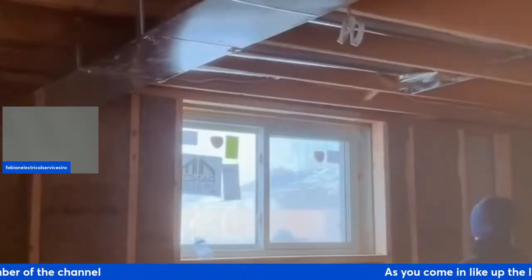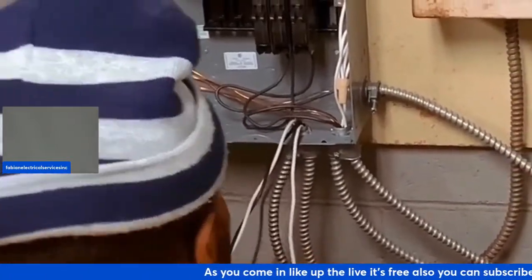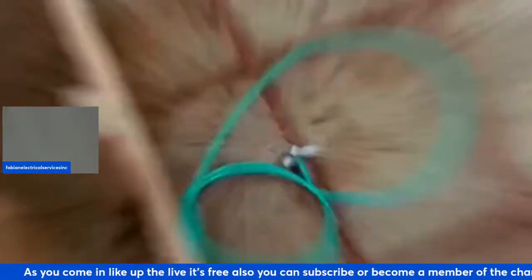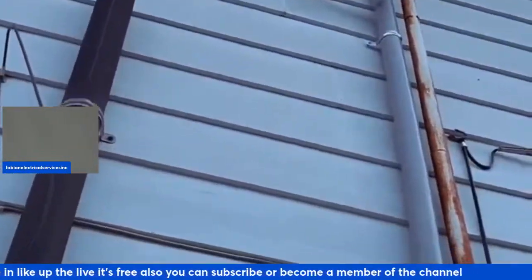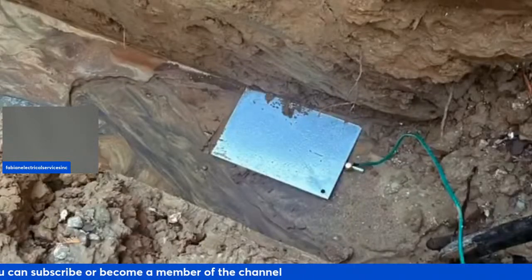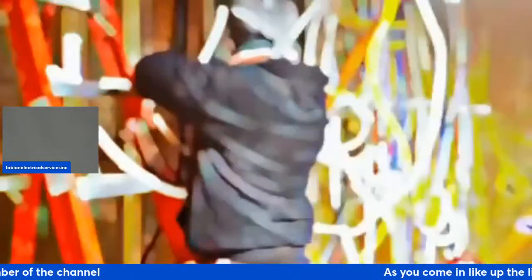And again, a dangerous arc is caused by damaged wiring or a loose connection, which can generate extreme heat. So when a dangerous arc is detected, the AFCI de-energizes the circuit, similar to how a standard circuit breaker works, but with the added ability to identify and respond to arcs.